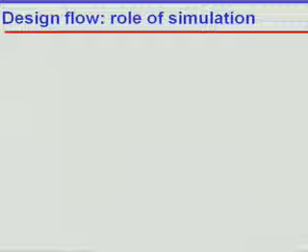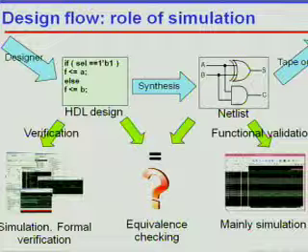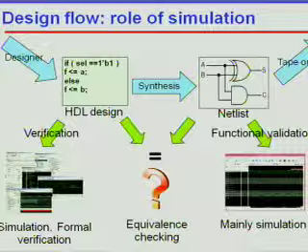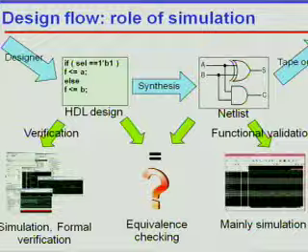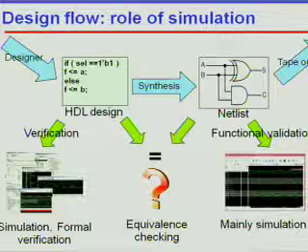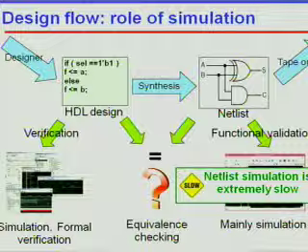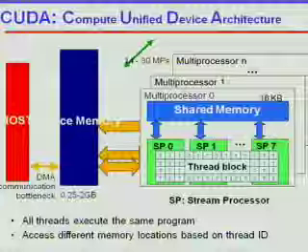So, what is simulation? For a hardware designer, when he designs the network using HDL, we need to synthesize it and verify it. The main part is that we need to check the equivalence of the function and our original design. That is mainly simulation. But the problem with this part is that the netlist simulation is extremely slow. That is just the problem we want to solve.